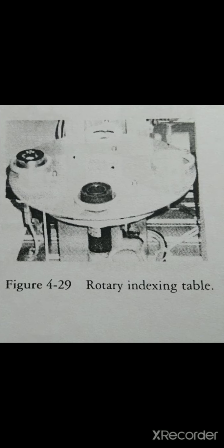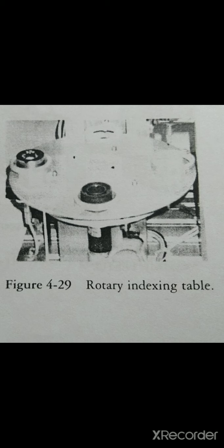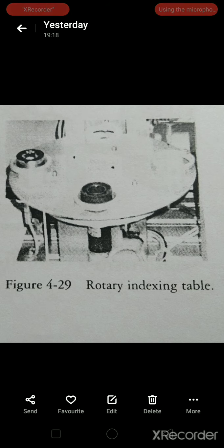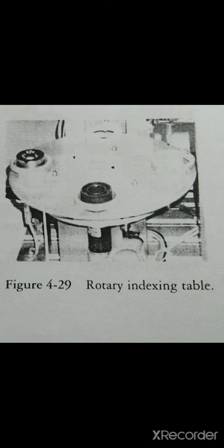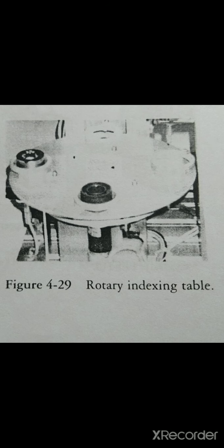Now on your screen is a rotary indexing table. In many manufacturing processes, it is necessary to carry out feed motion in a circular path. Rotary indexing tables are used for rotary indexing work with a high level of indexing accuracy on automatic assembly and packaging machines, embossing and marking equipment, and drilling stations. The powering device in a rotary indexing table is the pneumatic cylinder, used in conjunction with an air control block, which controls the movement cycle.